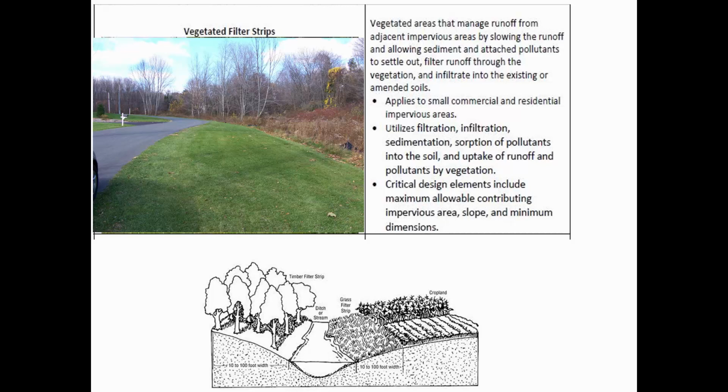So what this best management practice is showing is a vegetated filter strip. What that is essentially is just a grassy area by the side of the road where water is forced to flow over the surface before it gets into the ditch. They could have put a ditch or a curb immediately adjacent to the roadway, but by doing that, you're immediately channelizing the runoff. Instead, it's better to have a little bit of sheet flow before you go to channelized flow, because channelized flow is fast.